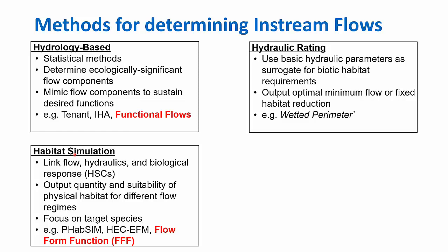So what you're doing is going at a river, the river that you have in your mind to restore it, and then in that specific reach, in that specific portion of the river, measure the bathymetry, the topography under the water of the river, and then run some estimate of the spatial distribution of velocities and depths at different flows. At a small flow, how much is inundated and what is the velocity of the region that is inundated.